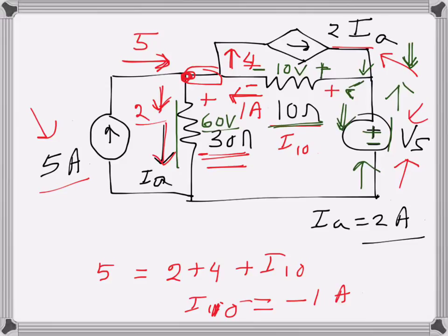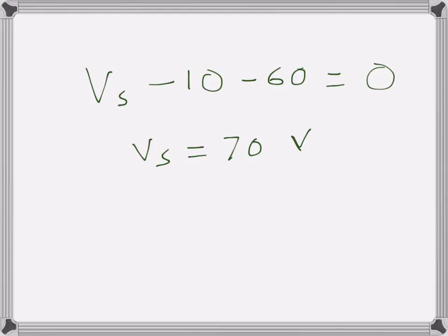So this voltage source is actually not delivering power, it's absorbing. So basically for a voltage source, if this is the voltage direction, the current should be in this direction when it is delivering power. But when the current is going in this direction, it is actually absorbing power.